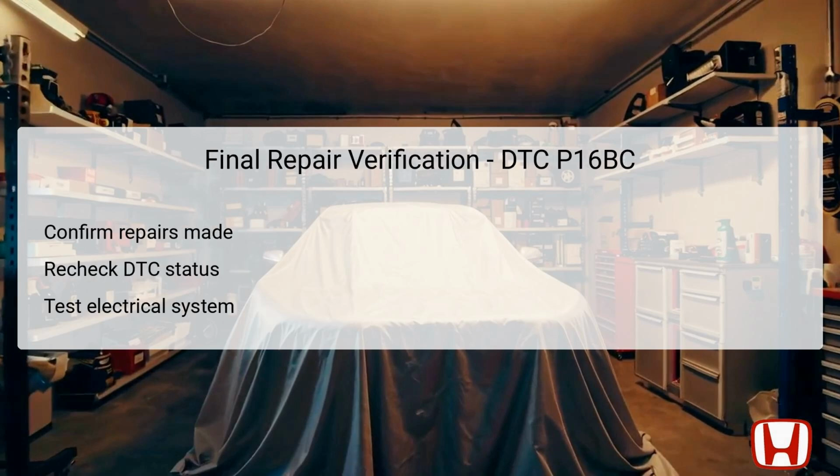After completing all repairs concerning DTC P16BC, it is crucial to verify that all are properly executed. Confirming that all connections are securely fastened, terminals are clean, and the alternator is mounted correctly provides assurance of quality work. Following this, recheck the DTC status using the HDS to ensure that the original code does not reappear.